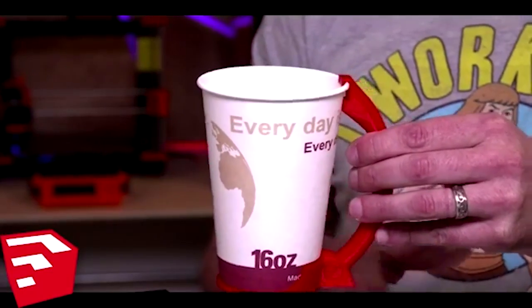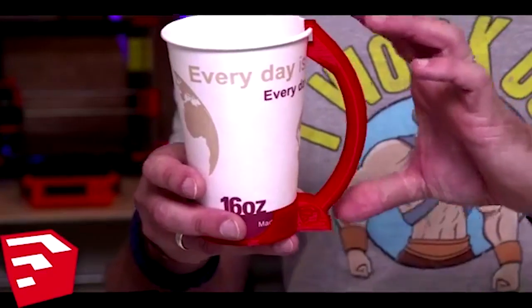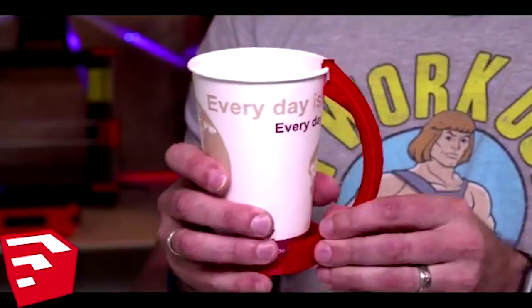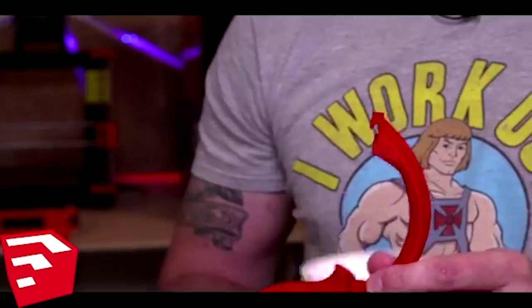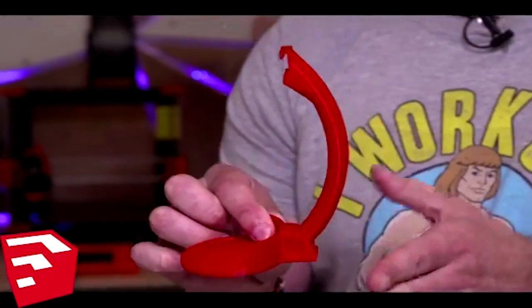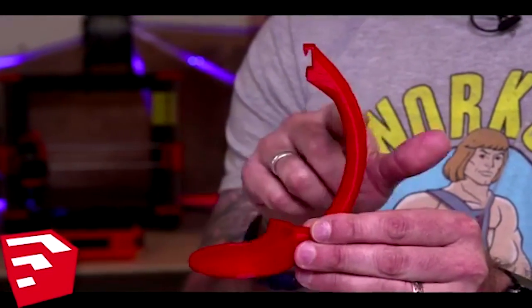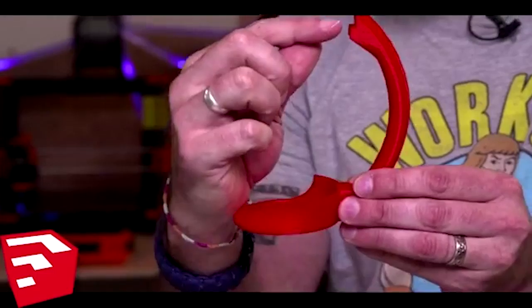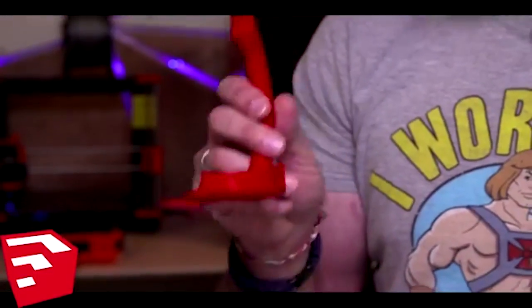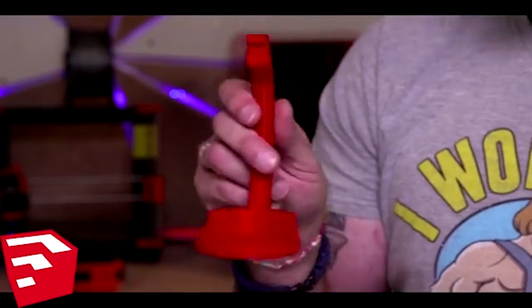They worked the same, but we were able to go through an iterative process to optimize the handle so that this was printed with less material, printed a lot quicker, and not only that, it prints without any material support at all. So the arc of the handle is such that it doesn't actually need any support as it builds up. The only support comes into this little clip right at the top, but other than that, the whole thing is printed without support. Again, not the first print, but the 5th or 6th time actually got it to that point.